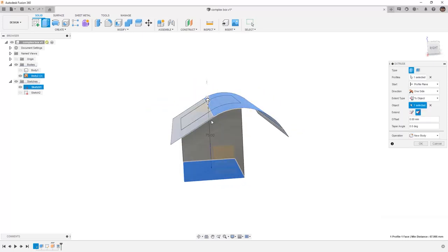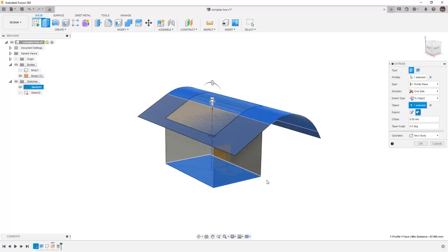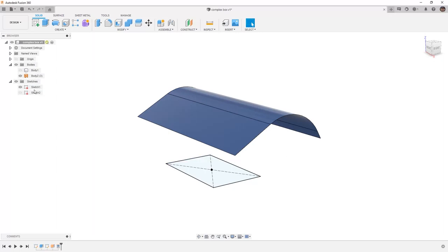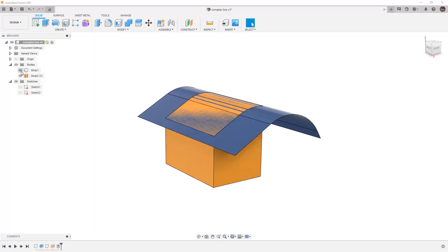in some cases it actually wants to carry that arc around. Fusion 360 is intelligent in the fact that it knows what we're trying to do and it extends the tangency of that edge out. But this doesn't work in all cases. In some cases, Replace Face might be the only option.